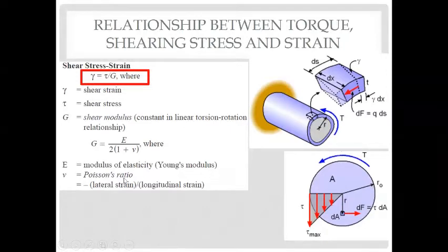And again, if you all remember, we're in which region? Elastic region. So basically, if you look at a stress-strain curve, that initial linear portion, if you go past that portion, basically, if you put a torque on this shaft, and that shaft cannot return back to its original position after you take that torque off, then you have exceeded the elastic limit of that shaft, of that material.